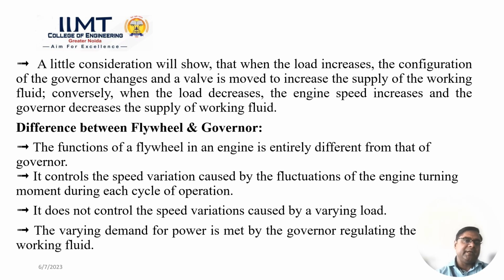So the flywheel plays a very important role whenever there is a cyclic variation inside the engine. In a single-cylinder engine a very big or large flywheel is required, and whenever you increase the number of cylinders, the flywheel size is also reduced.